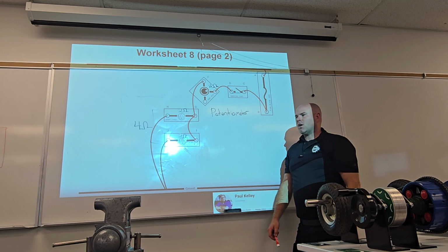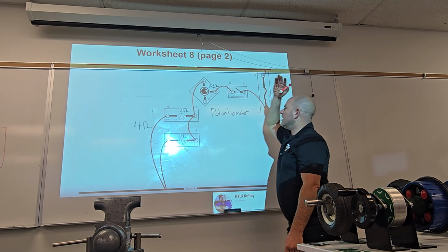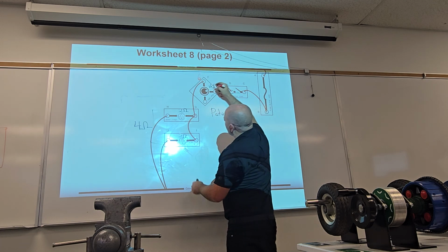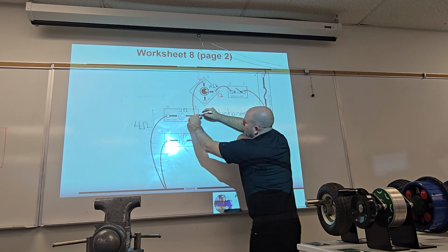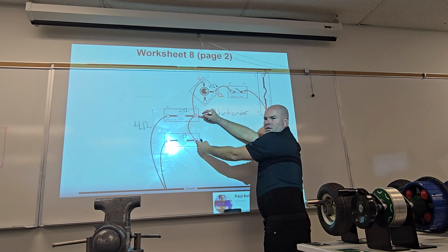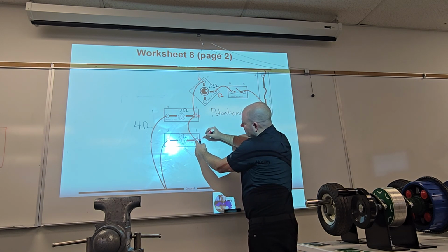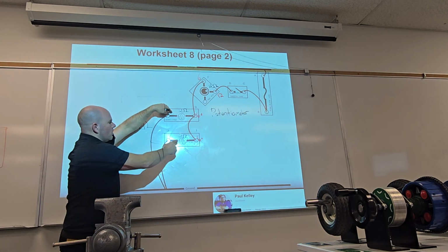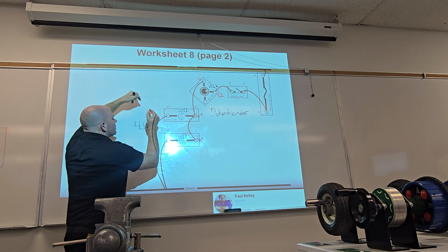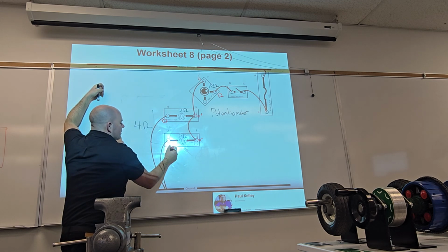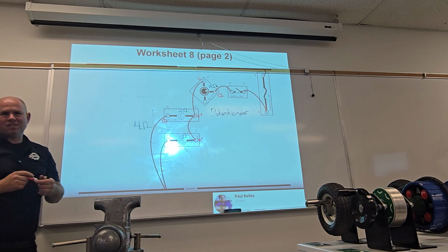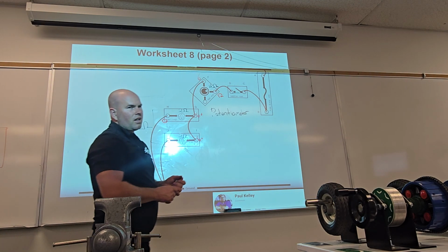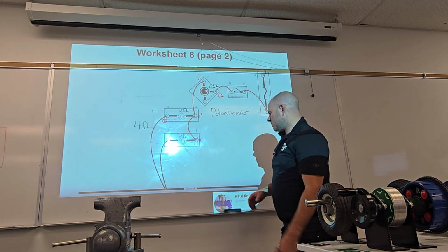Kind of, sort of? All right, but then if you were to break it down from there, if this one took half, so we agree it had 12 coming in, it has 6 coming out. But look, it has 6 right here, and then a wire coming down here, so this also has 6. And then these being their own loads, each is going to consume all of it. We're going to have 0 and 0. See how that one's just a little different when it's a series parallel? Yay or nay? Stuck on that one? All right, then let's make it even worse.